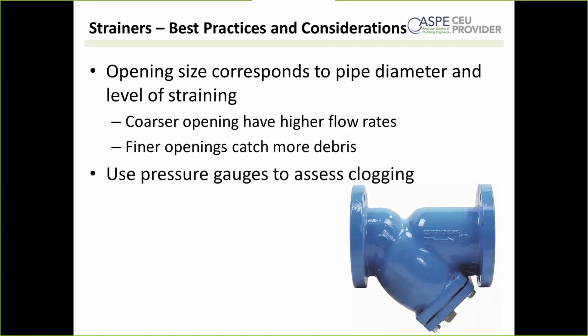Second, it is best practice to install pressure gauges immediately upstream and downstream of the strainer. This is going to help you to assess clogging.